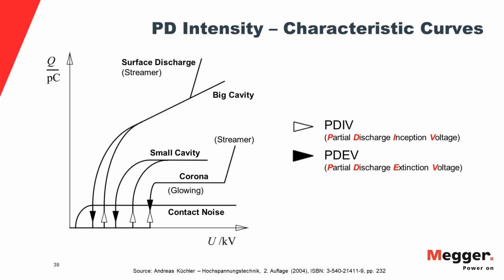And now just something about the intensity. What you want to see during PD testing, you're measuring various key parameters, and the most key parameter is the partial discharge inception voltage, PDIV, followed by the PD mapping, the intensity at U0 that comes out of IEC. The discrimination of the criticality should be done at operating voltage U0. And then there's PD extinction voltage. You trigger an event. When does this event stop again? Or does it stop at all? That is kind of the relationship.